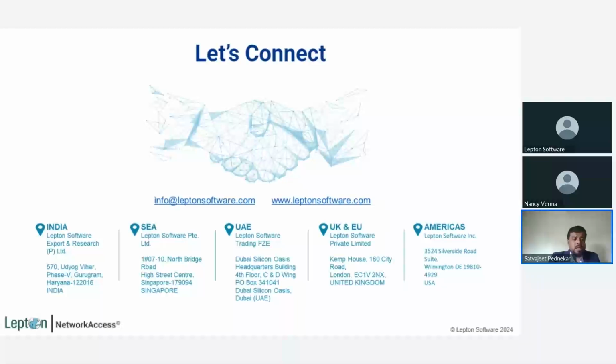This stage can be achieved with the help of the planner and the surveyor. The surveyor does the survey and the data comes to the smart inventory tool. The planner can visualize it over the map and see the actual location of the home passes. It's the planner's job to find out which home passes are missing by visualizing the maps. That is the only way right now to do it, and it can be achieved with the coordination of the surveyor and the planner.